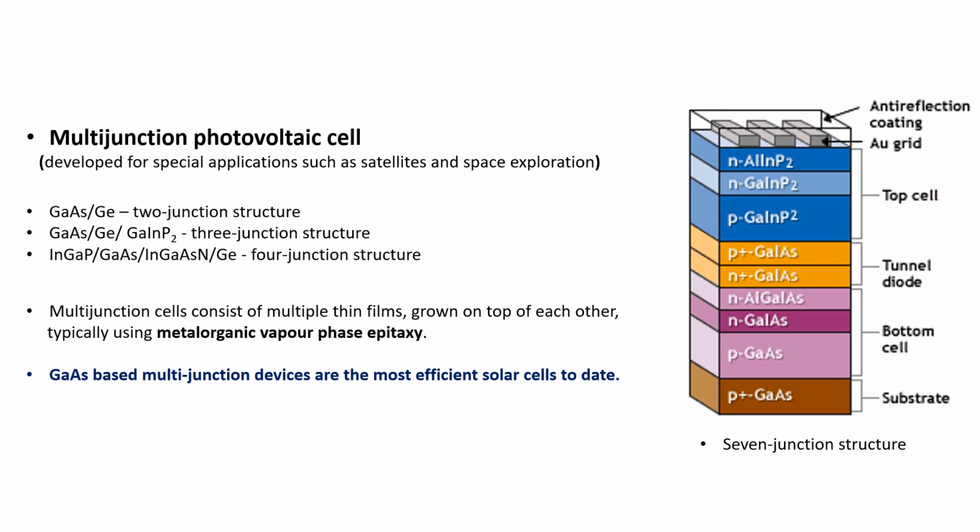Actually, more precisely, it allows absorbing and converting the photons that have energies greater than the band gap of that layer and less than the band gap of the higher layer. Such multi-junction solar cell structure requires materials with optimal band gaps which simultaneously allow high efficiency through low defect densities, and very good candidates are the alloys of group 3 and 4 of the periodic table.